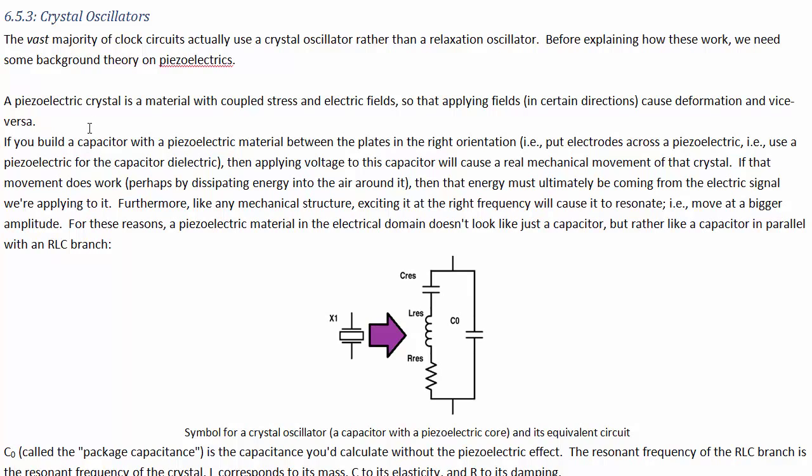Piezoelectrics are special kinds of crystals that have just the right kind of charge and structure asymmetry, so crystal asymmetry and charge asymmetry, to couple their stress fields to their electric fields, which means that electric fields create deformations in them and vice versa, deformations create electric fields. So if you were to build a capacitor and use a piezoelectric as the dielectric for the capacitor, as the material between the plates, then when you apply a voltage across it, you cause the piezoelectric to move.